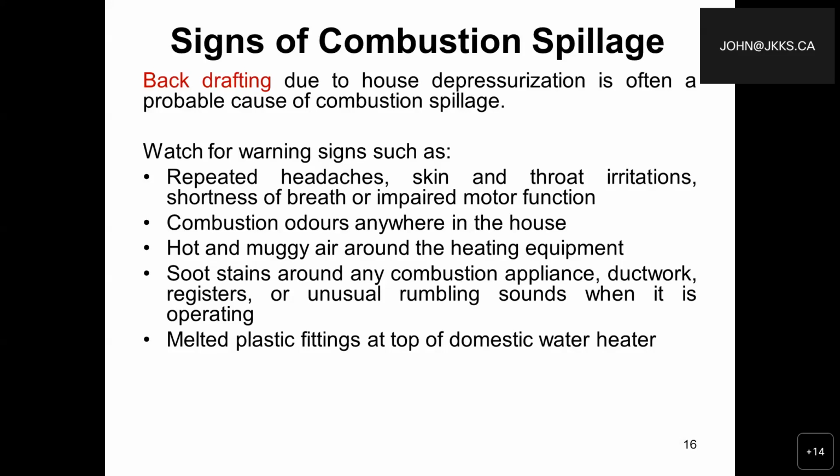Of course, some of the things we need to think about is watch for warning signs such as, again, from a personal point of view, headache, skin, throat irritations, shortness of breath, or impaired motor function. Are there any strange combustion odors anywhere in the house? Is it hot and muggy air around the heating equipment? Are there soot stains around the combustion appliances, that I mentioned earlier, or melted plastic fittings at the top of the domestic water heater?